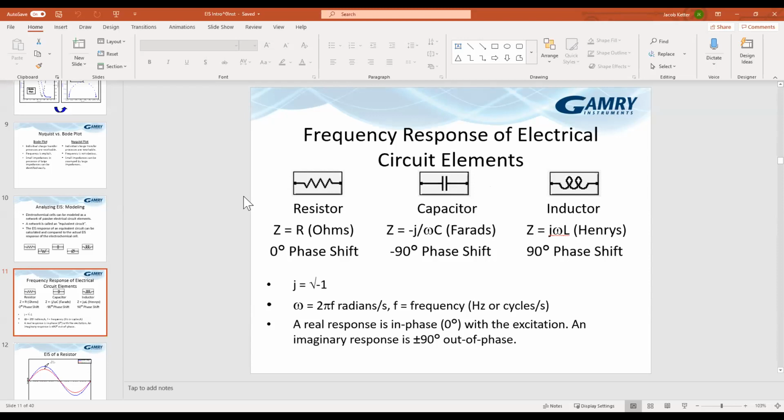There are different classes of inhibitors, and knowing which one you're working with makes a difference, right? So some inhibitors are going to inhibit the anodic reaction, others the cathodic reaction, and others are almost like coatings themselves. They are laying themselves down and providing a barrier to active areas on the electrode surface to things that are out there that would otherwise stick to them and cause corrosion.